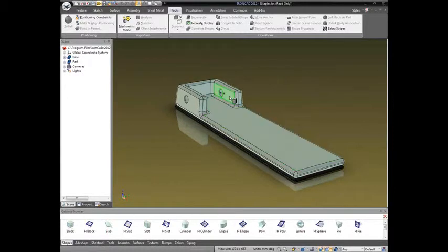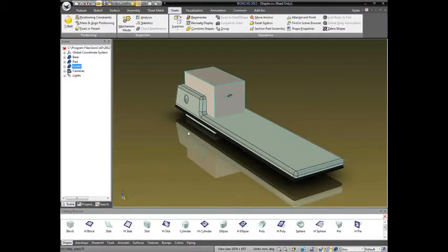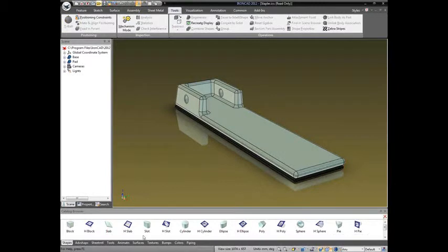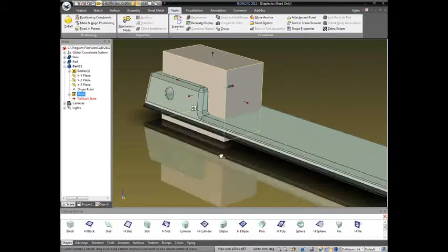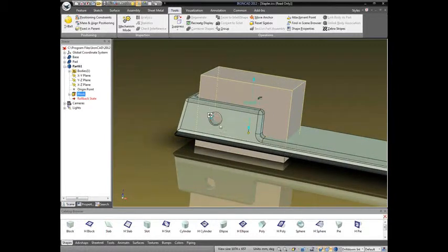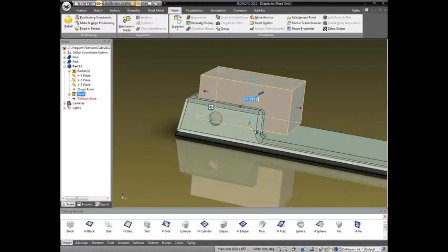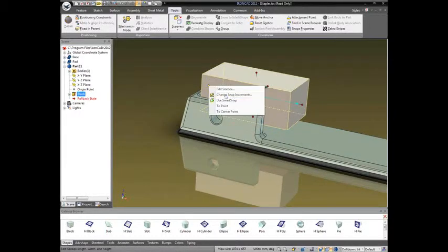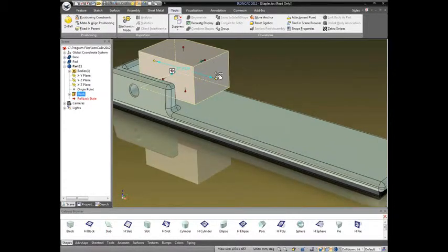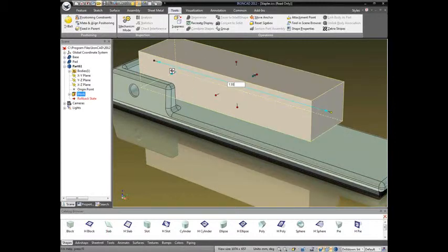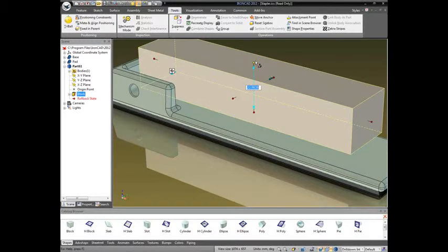So I'll drag and drop a block out here just to put it in place and drop it as a part. And you see the first thing I did is I forgot to set structured part. Here we go. Structured part mode, do it again, and I get the structured part that I wanted. So most of the things you're used to are still there. The drag and drop handles, you can come in here and do similar manipulations. So I'll go ahead and snap that in place. I'm going to make a little cover for this stapler, is the idea of this tutorial here.